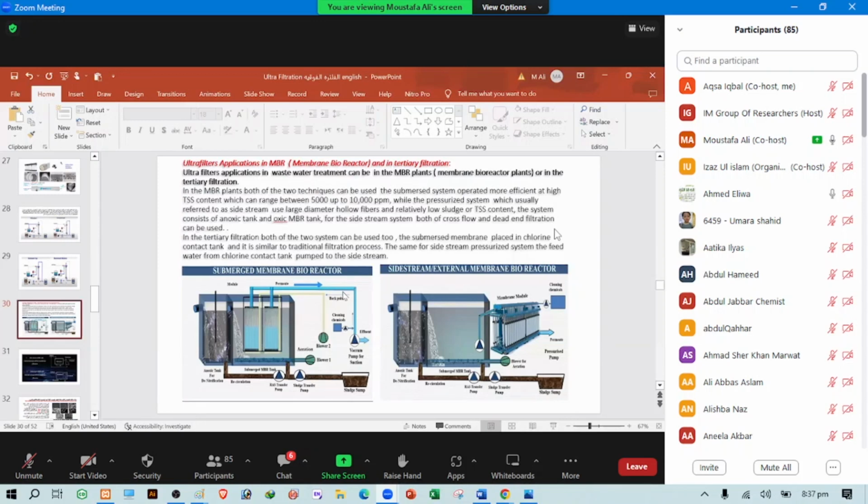Backwash also, you understand? It's not a separate pump. We use just a control valve. In most cases of filtration application, we are saving a little bit. Yesterday in the demo version, which shows two pumps, one for sucking, one for backwash, we can actually use only one pump and just the valves play.